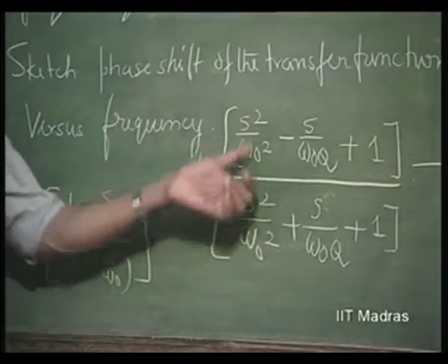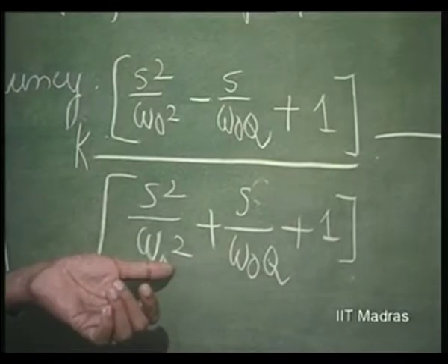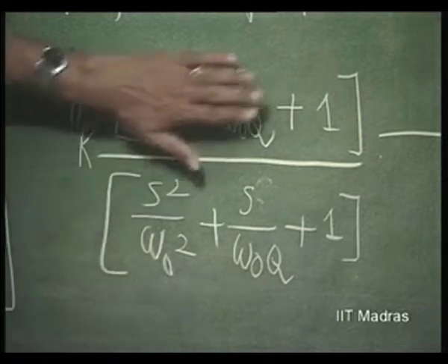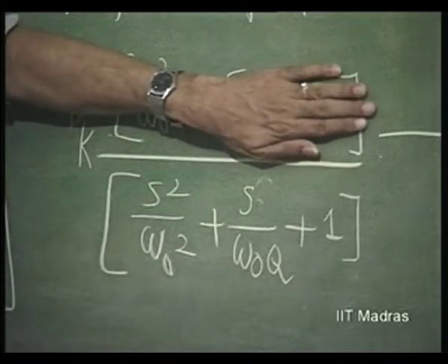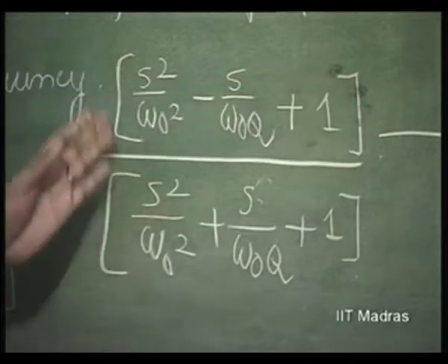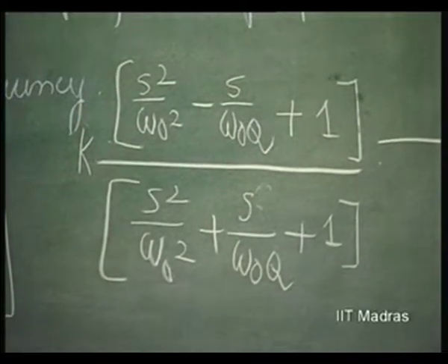A second order all pass will give you a phase coverage of 0 to 360 degrees. Now, that can be concluded: the pole alone can give you a phase shift from 0 to, s squared means minus omega squared, 180 degree, and addition will have 0 also contributing another 180 degree.